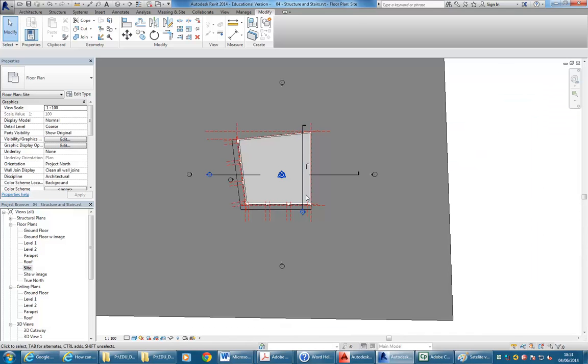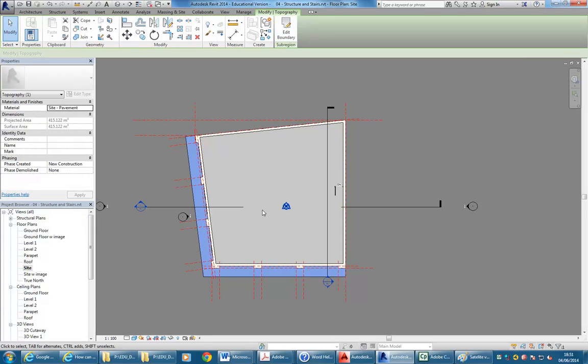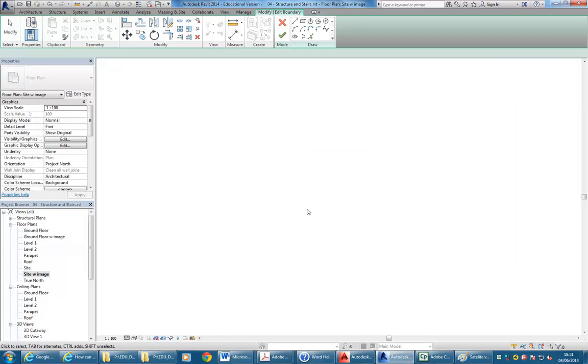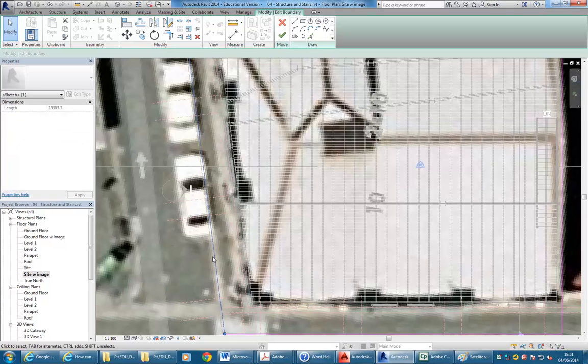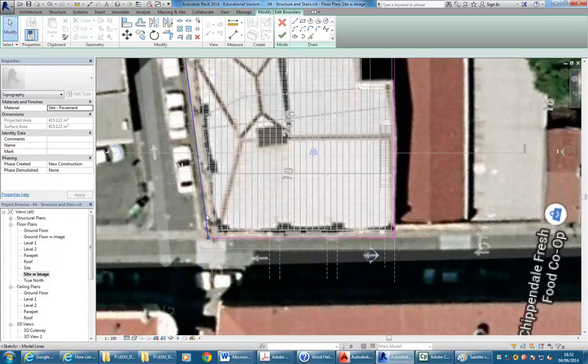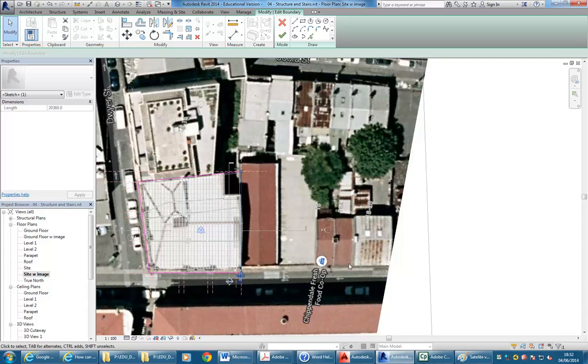And maybe just to give you some more examples, when you go back to edit those, you do need to be a little bit careful, because if they overlap, they won't work. You can have as many subregions as you like in a topo surface, but they can't intersect. They can touch, but not overlap. If I go to edit boundary here, I'm just going to fine tune that against my image. Well, it's probably not very wide actually, this footpath, because it's a lane. Okay, and then I can probably, with these buildings, stretch it out and then model over the top of them using just very simple massing type models. That's always a good thing to have. So I'll just finish this one.